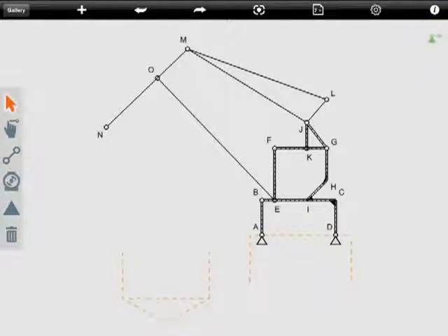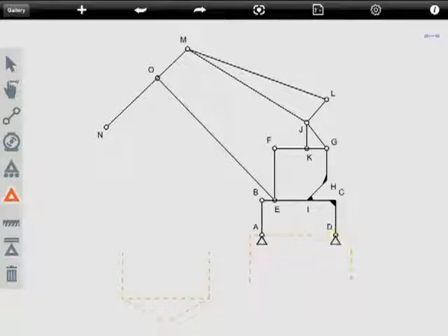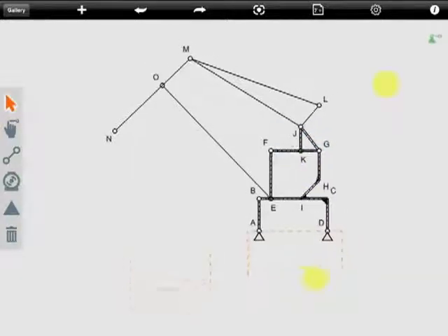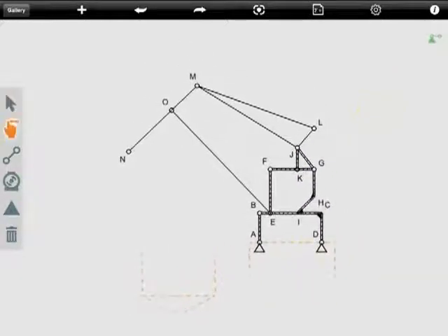During design, the degree of freedom indicator in the upper right-hand corner changes progressively. For predictable motion behavior, we recommend creating a mechanism with 1 degree of freedom, which is indicated by the green degree of freedom symbol. Also notice the base of the crane changed to a double line, which indicates that the element is constrained in place and will not move when the system is animated.